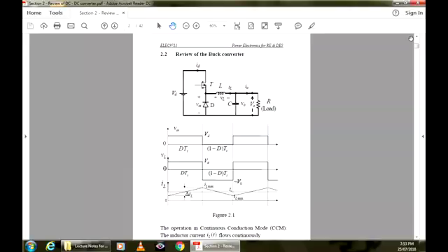Okay, so our assumption is that energy flows from the DC source to a DC load, and we assume that the DC load is supplied at constant voltage. So the voltage remains constant. Energy goes from a DC source, so the current through the inductor will have a DC value. In each switching cycle, the volt-second balance, that means the L di/dt voltage across the inductor, must add up to 0. There will be no steady DC voltage across it. If there is a net DC current flowing through it, there will be no voltage across it in the steady state.